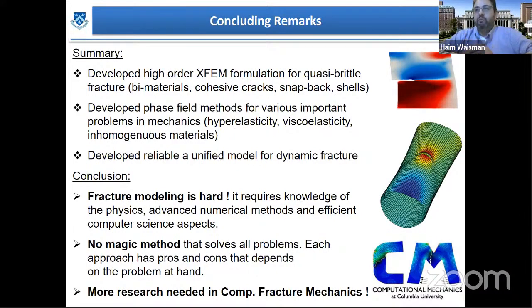Otherwise, the only thing that will provide a length scale is h, the element size. And actually the element size does depend on the wave speed, right? So in some convoluted way, it does provide a length scale, but it's not the correct length scale, because you need to have this length scale not as a function of the discretization that you have in your model, but from a physical point of view. Hope I answered that question.